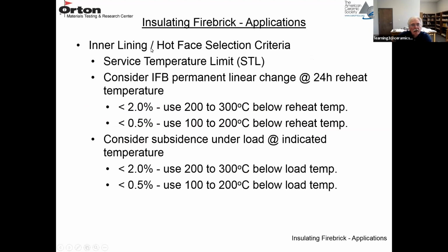So, inner lining, hot face selection criteria. You have to be aware of the service temperature limit, abbreviated STL. Consider the IFB permanent linear change test, which I will go over shortly. It's a 24-hour hold at temperature, so it's a 24-hour reheat test.